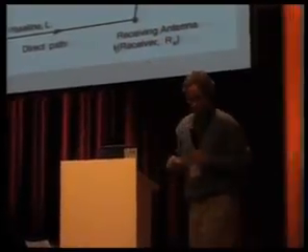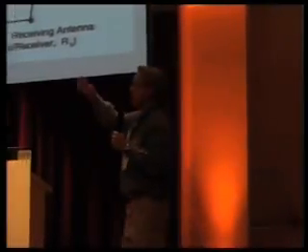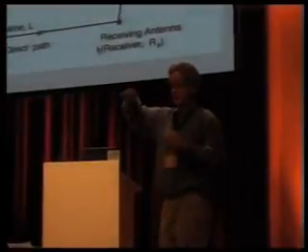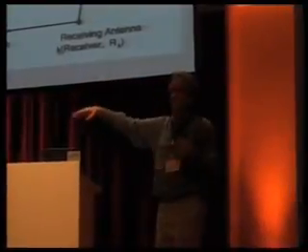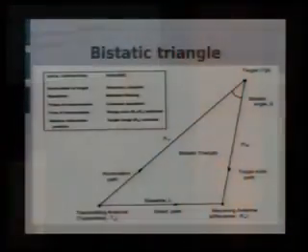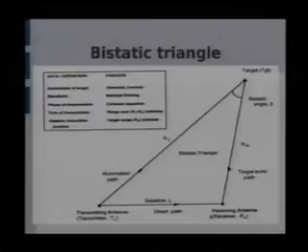So if you start thinking about what you can do with this, if you have a pulse, you could measure the leading edge of the pulse, and you would see the pulse come twice. You'd see it come once really loud, just kaboom. That's the direct path. And then you see a delayed version of it that comes sometime later. How much later is basically the difference in these two path lengths. So you've got the short path, L, and then you have the long path, RT plus RR. You know the speed of light, and you know this difference in time. So this starts to show how you can begin to put the solution together.